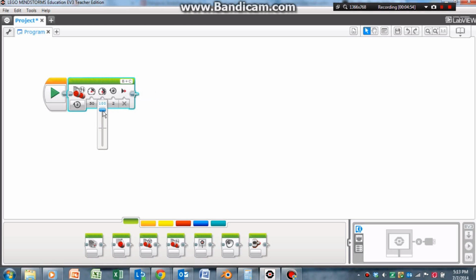The unique thing about this specific block in LEGO Mindstorms is that you can control the power of both the different motors. For regular blocks like this, you'll notice that it only has one power value, which means that both the wheels move at the same speed. But using this specific block, you can make both wheels go the same power, different powers, and even in opposite directions. For example, I have port B, which is the power of the left wheel, B.